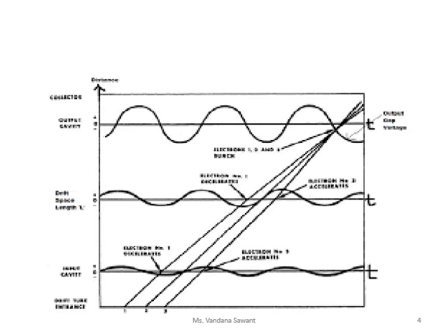If you see the total process here, initially the electrons which are moving from this buncher cavity will travel a distance L, and when they reach the catcher cavity, if you see the top waveform, there is a negative half cycle. Because of this negative half cycle, maximum energy from the electron will be extracted by this signal's negative half cycle, and the maximum energy is given to the cavity, that is inside the catcher cavity.